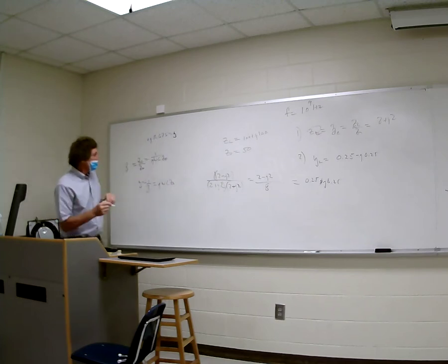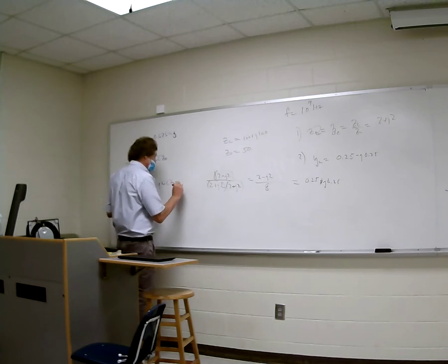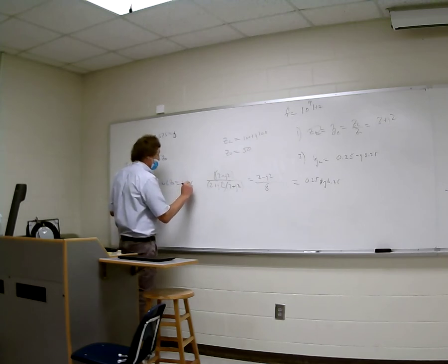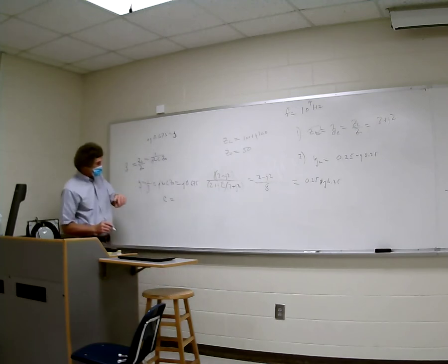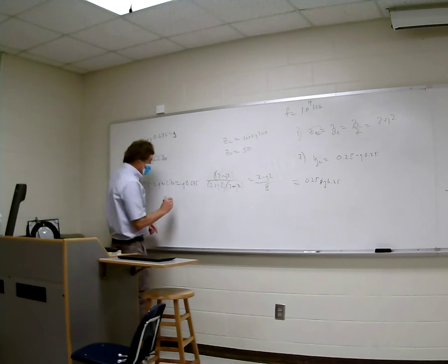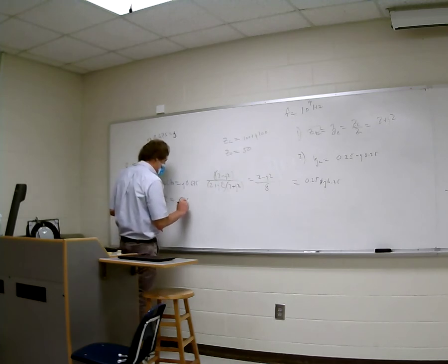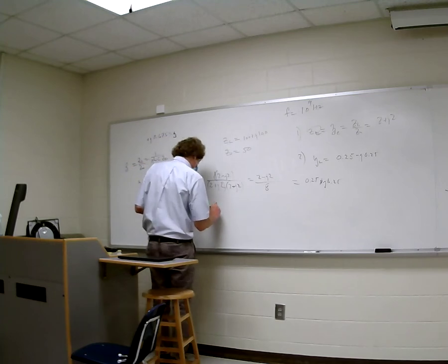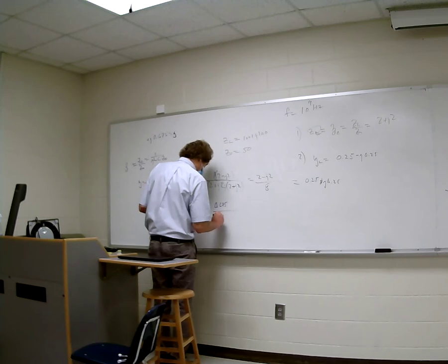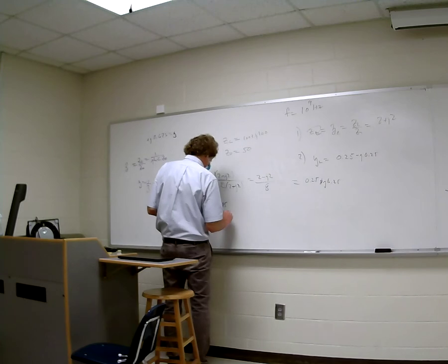We set that equal to this, j 0.675, and therefore we can say that C itself, the j's go away, would be equal to 0.675 divided by omega times Z naught, and for ours it would be 0.675 over 2 pi times 10 to the 9th, in hertz, times Z naught, and Z naught was 50.